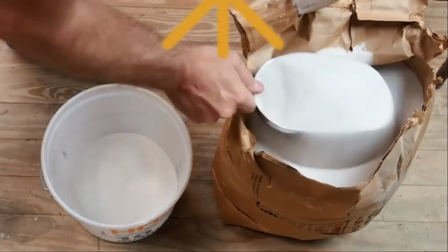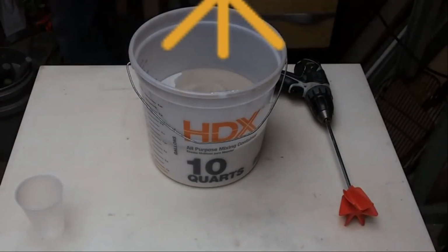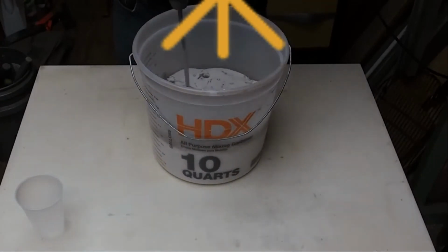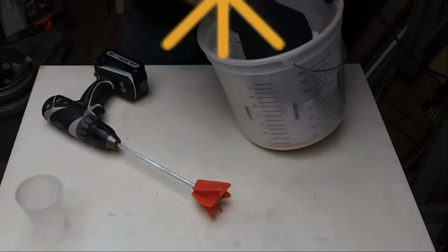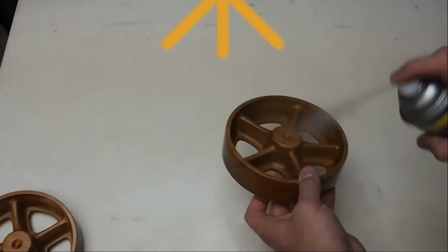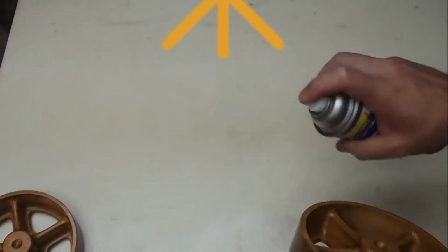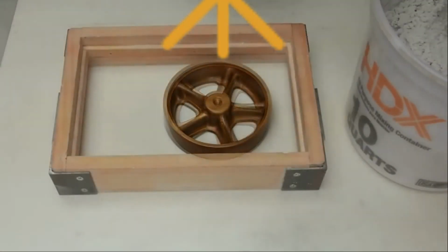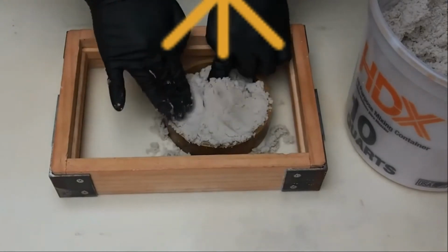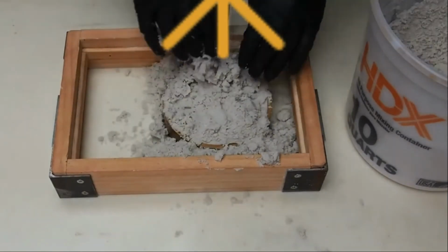Here I am using sodium silicate sand for the mold. I am hoping for a nice texture on the inside of the wheel to add to that old-timey flavor. After a few sodium silicate casts, I have found that actual mold release works better than talc for keeping the pattern from sticking to the mold. The texture of sodium silicate sand is a bit like mashed potatoes.